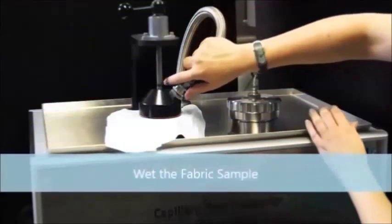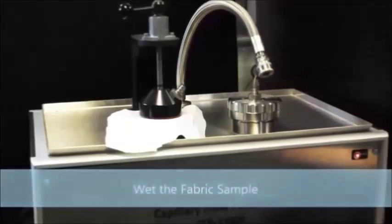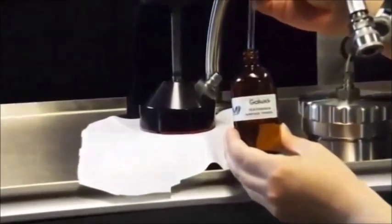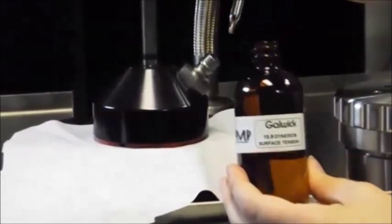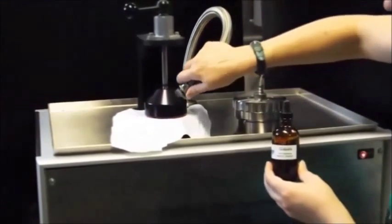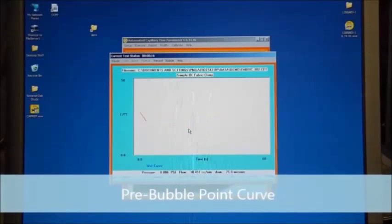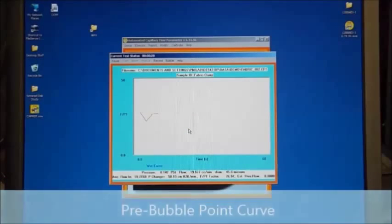To wet the sample, you can either remove the clamp or the hose, then pour wetting liquid onto the sample, click the OK button, and that will start the wet test. Depending on the test area, only a few drops of wetting liquid is usually necessary to wet the sample. Once you've clicked the OK button to start the wet test, now it'll begin the pre-bubble point test,